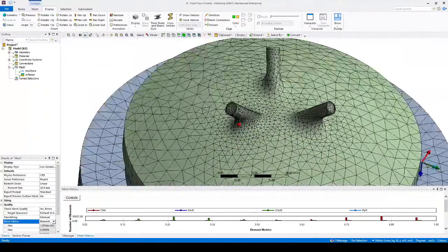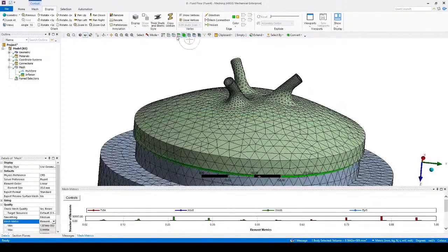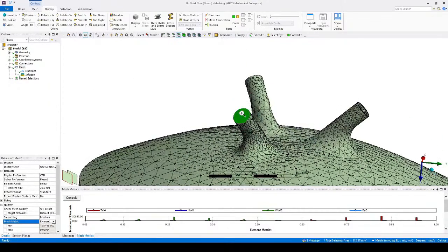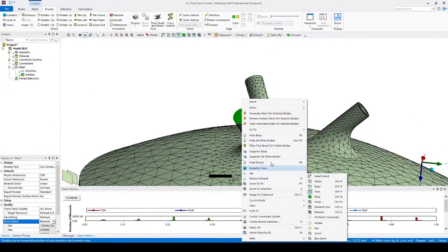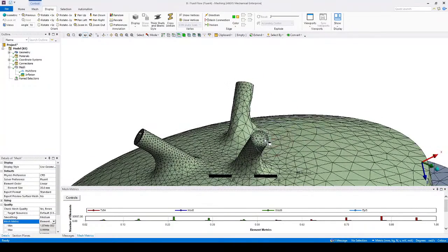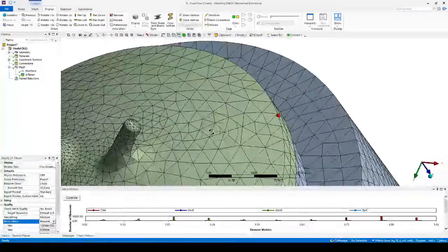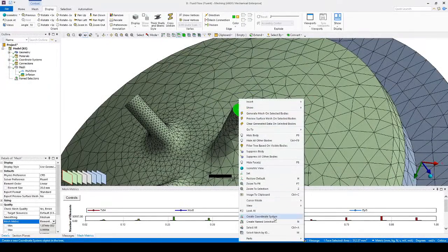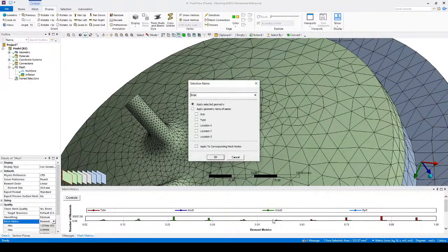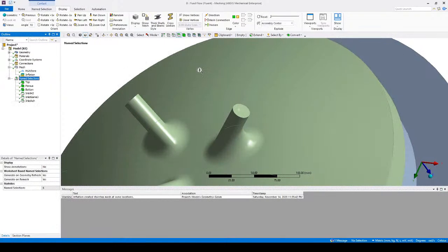So that's the volumes. This allows us to specify porosity behavior in the porous region here. Now we want to specify the inlet and outlet boundary conditions. So let's create this, this will be an inlet. In this one, we'll have H2 pumped in, another port we'll have GaM3, and then in this port, AsH3. Okay. Let's double check, make sure we got all of them set up here.